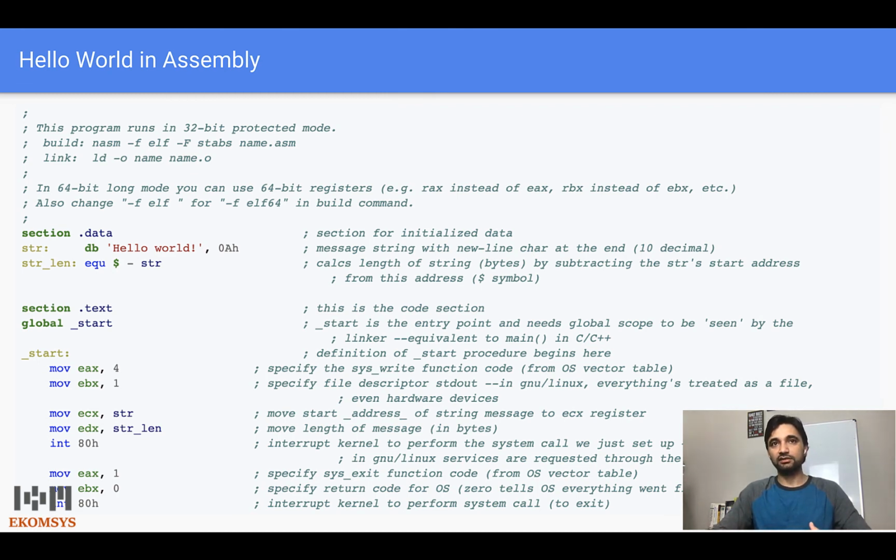So, as I already mentioned, we have a program counter, which is the current instruction that the CPU is executing. Whenever it gets an interrupt, it will save that PC on the stack, and then call your interrupt service routine, giving all the arguments. Once that interrupt service routine is executed, it will resume the execution by popping the address, the program counter in this case, from the stack.